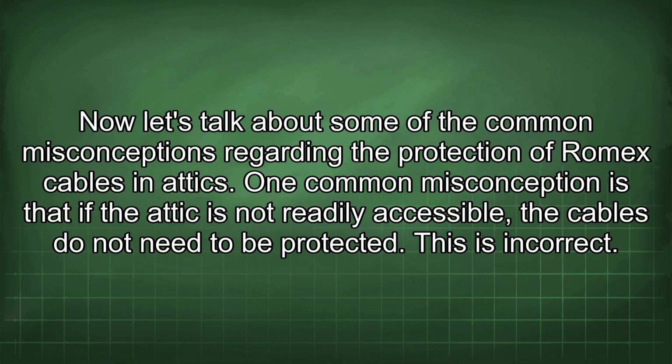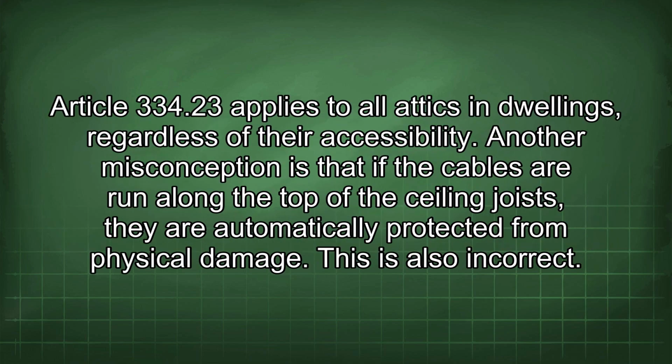Now let's talk about some of the common misconceptions regarding the protection of Romex cables in attics. One common misconception is that if the attic is not readily accessible, the cables do not need to be protected. This is incorrect. Article 334.23 applies to all attics and dwellings, regardless of their accessibility.